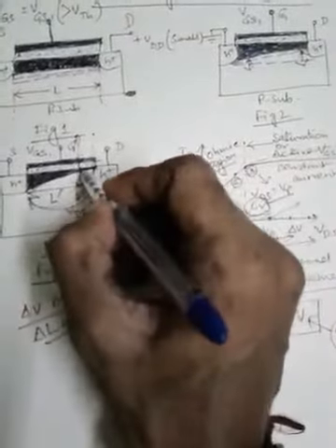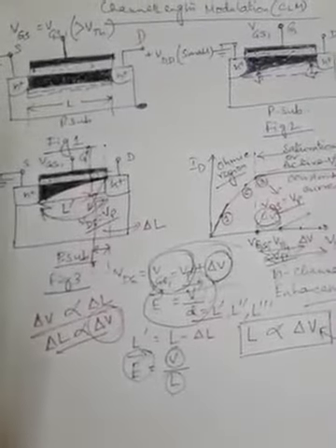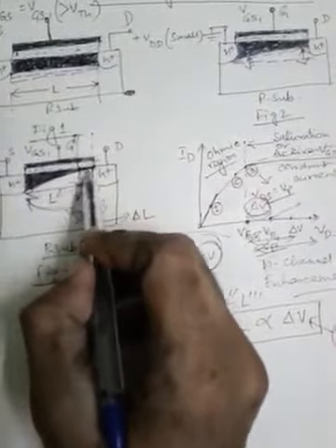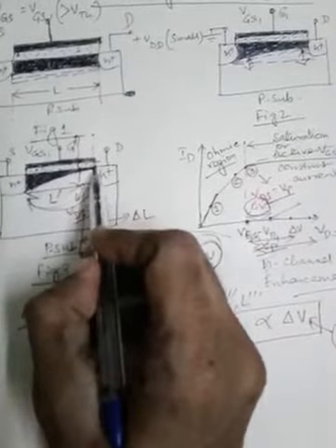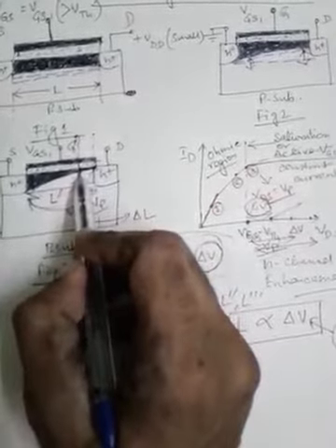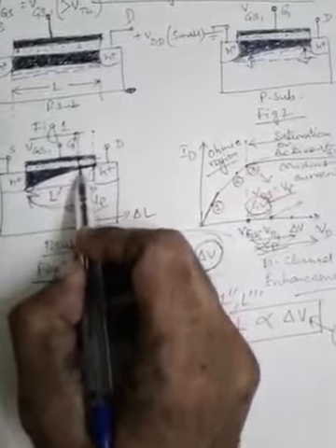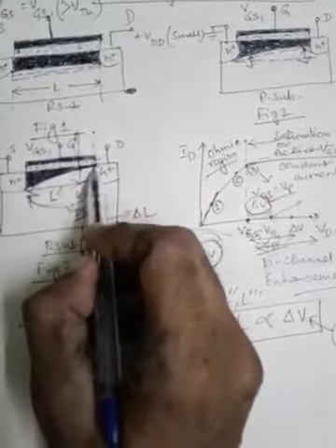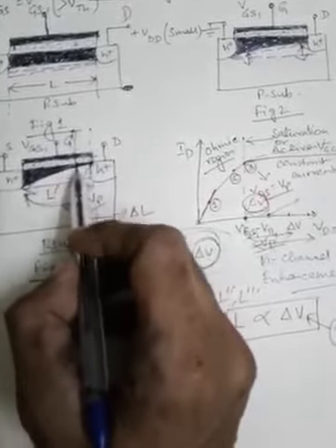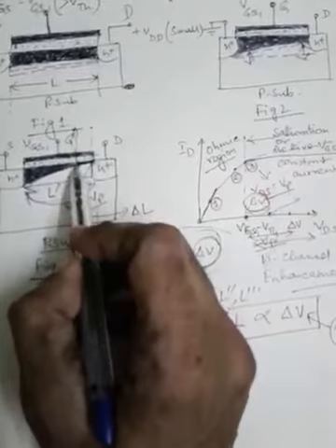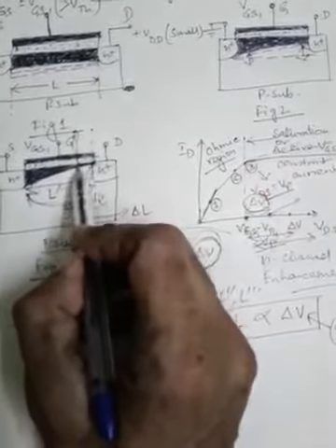Although due to the reduced channel length the pinching off is happening over here rather than over there as in the previous case, since it is now happening earlier, from this point the electrons need to complete their journey up to the drain terminal.